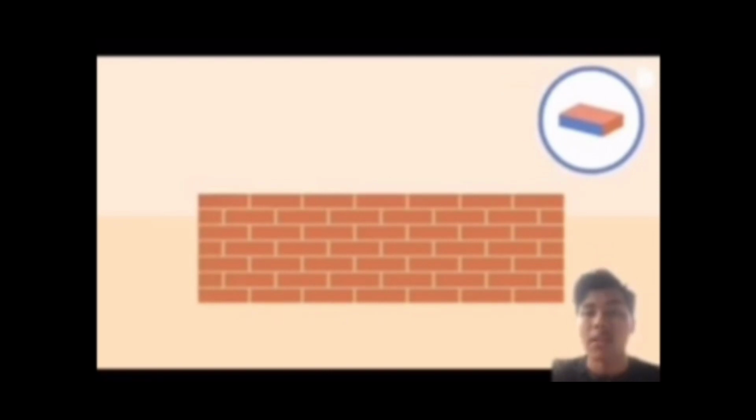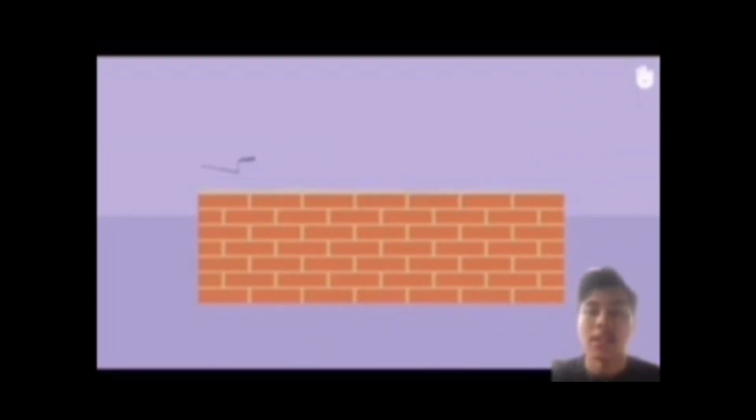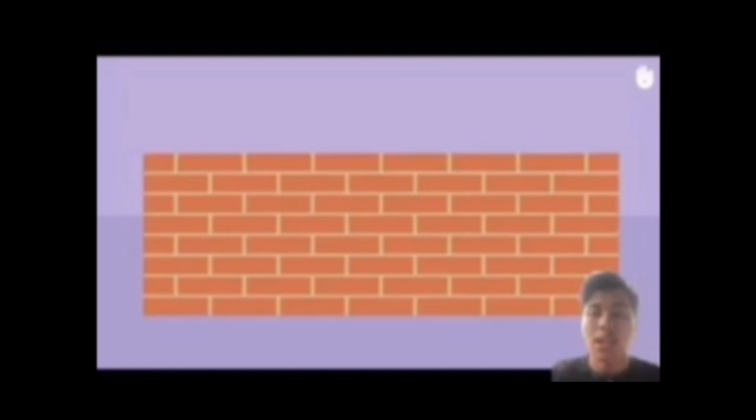English bond. This alternates courses of stretchers and headers, with the alternating stretcher course being offset by half a brick. The stretchers are centered on the joints between the stretchers below them, so that the alternating stretcher courses are aligned. Staggering stretchers enables patterns to be picked out in different textured or colored bricks.